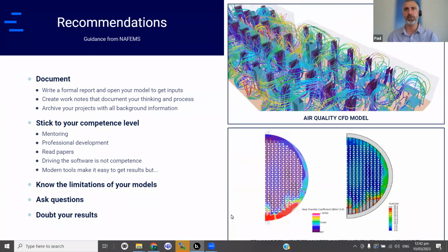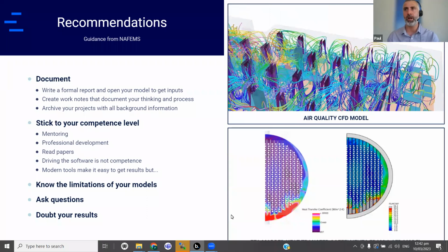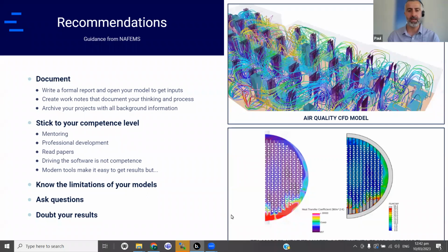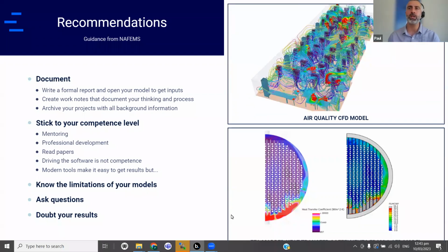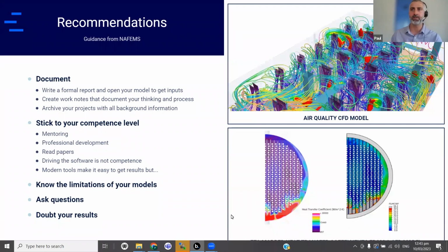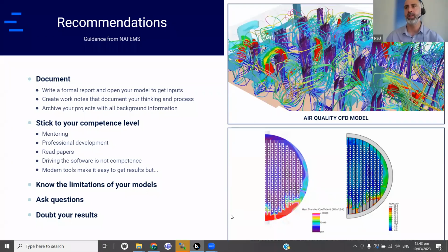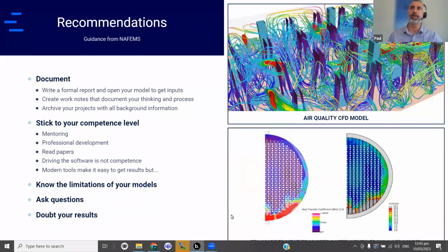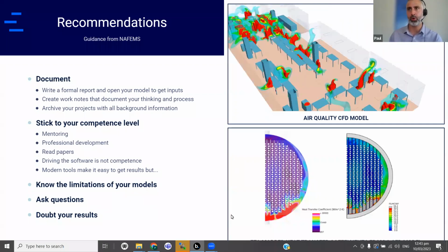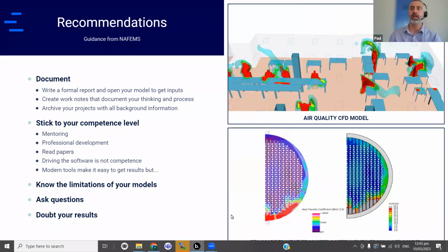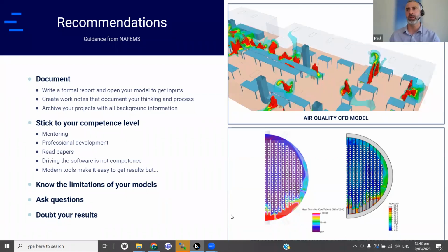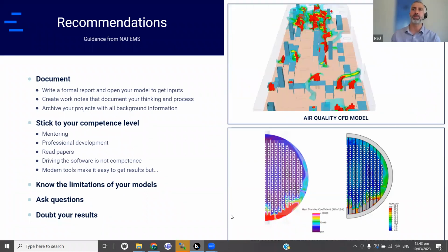because I personally have a huge interest in it and I'm watching it closely. I think it's still in the watch-the-space approach. Right now the state of the art with AI and CAE is machine learning. If you're doing one class of problem all the time, you could run 100 or 500 simulations and build up a data set, and then you ask the machine to learn about that data set. Once it's analyzed that data set, you can almost in real time make modifications and get a result. That's very attractive, especially if you're looking for a 1 or 2% improvement, or doing something very similar that sits in the same space.